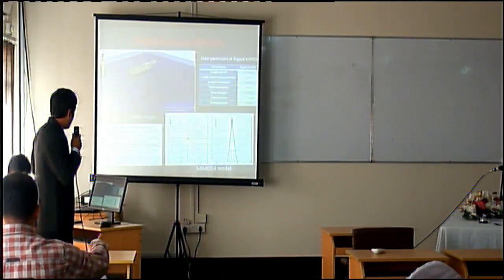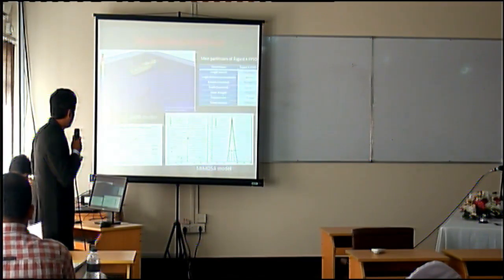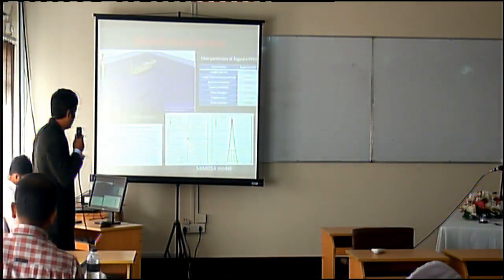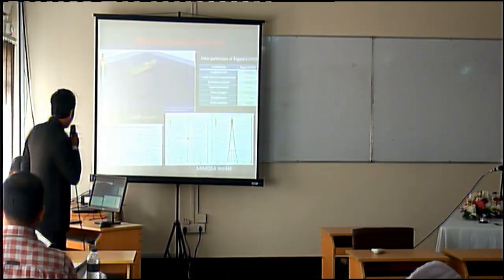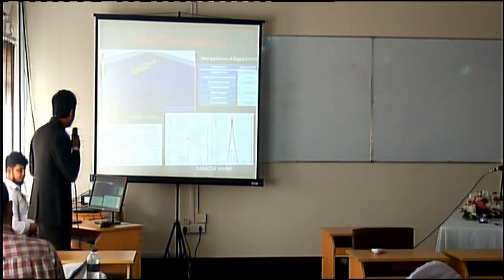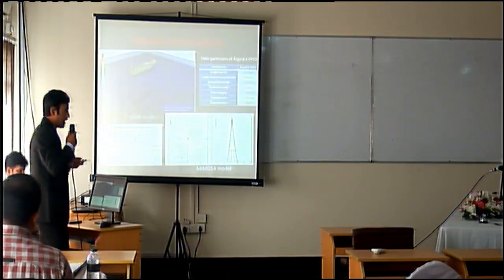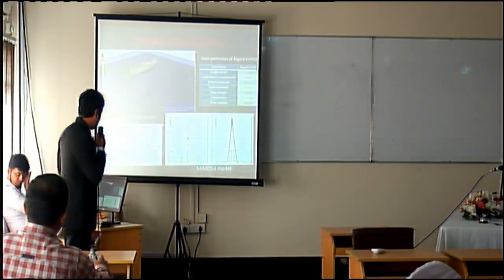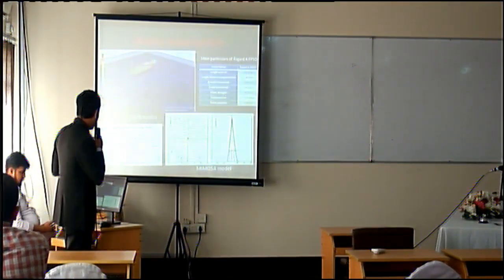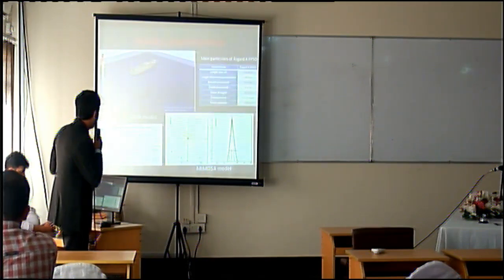As we are using two different models here, we need to verify that both of them act correctly. As proof of this, we calculated the mooring system restraining force and how it acts in the two different models. As you can see, they are almost the same in their behavior.